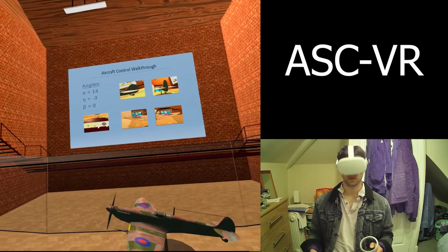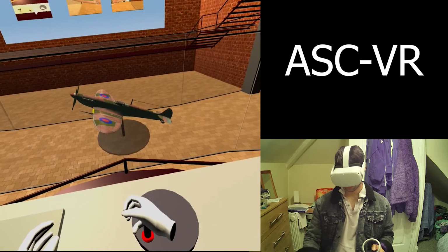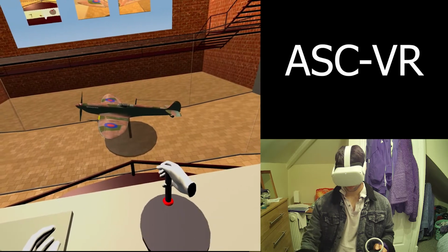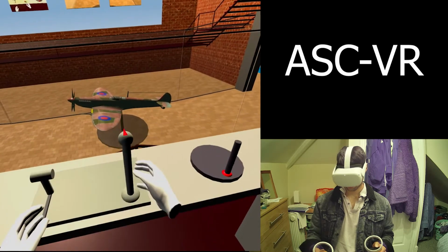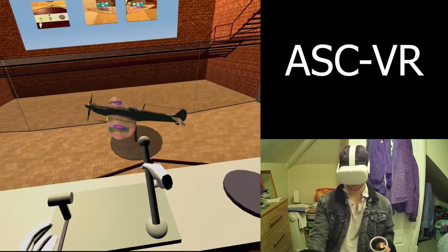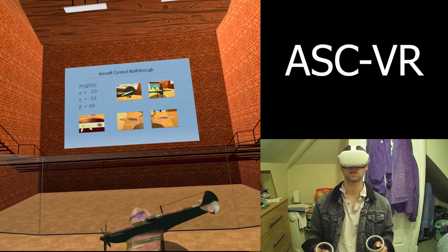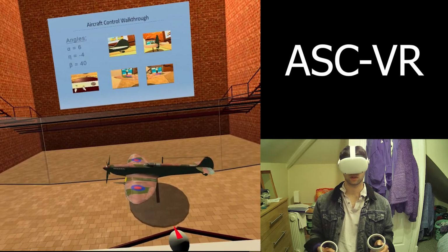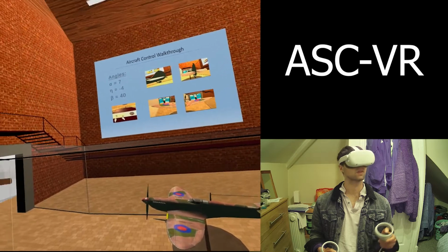This can be adjusted for by using the trim wheel to change the tab angle on the tailplane. Pushing or pulling the joystick forward or back changes the elevator angle on the tailplane and also pitches the aircraft up or down. Note how the rear lecture screen has live camera feeds of the control surfaces of the aircraft, the control panel, and the angle of attack, elevator angle and pitch angle of this aircraft are also displayed.